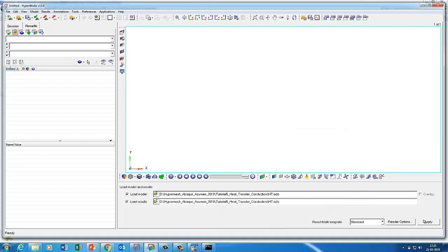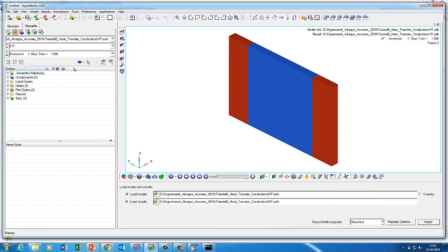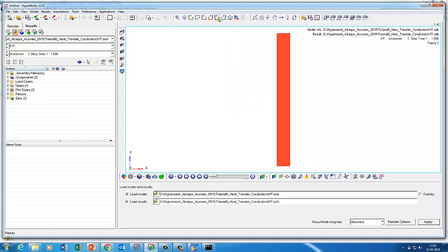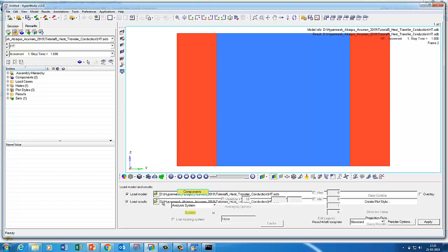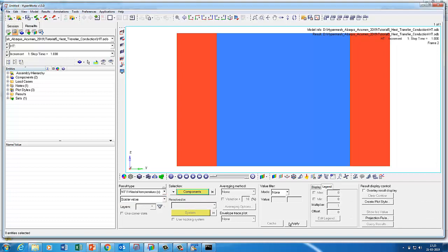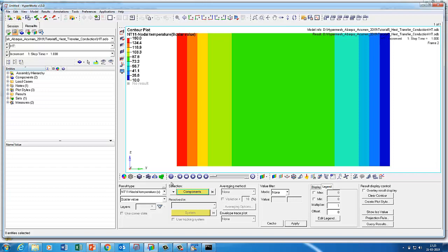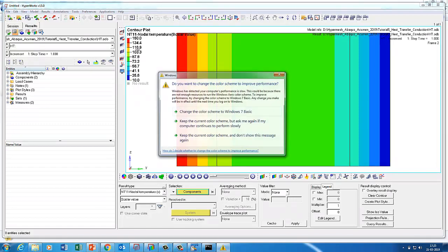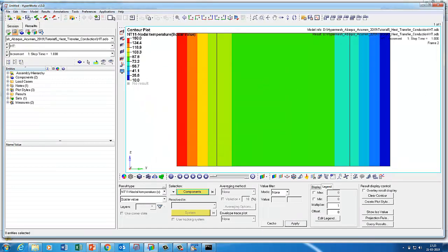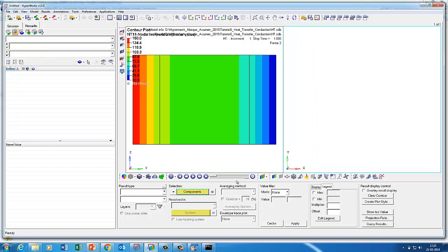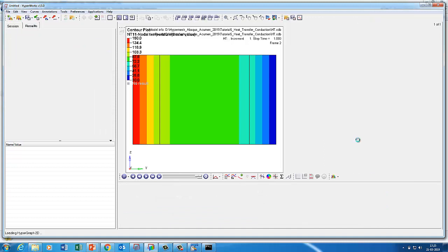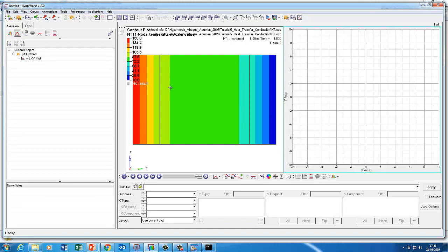So I'll take the ODB file and see how the temperature looks. So I'll just put in one particular view and then we'll measure how the temperature looks. So we apply the temperature. So if you look, you have 100. So we'll just try to plot it. So I just split this window into two. I'll use HyperGraph here, and then I'll take the temperature distribution across this.